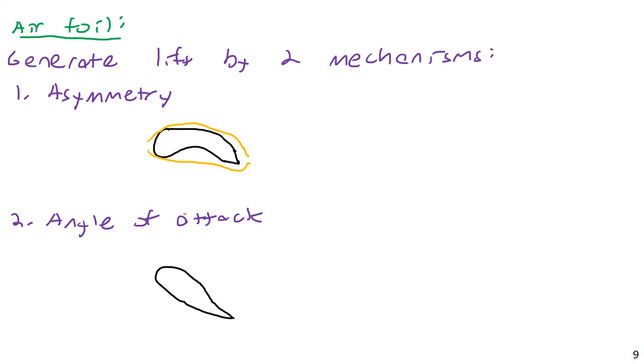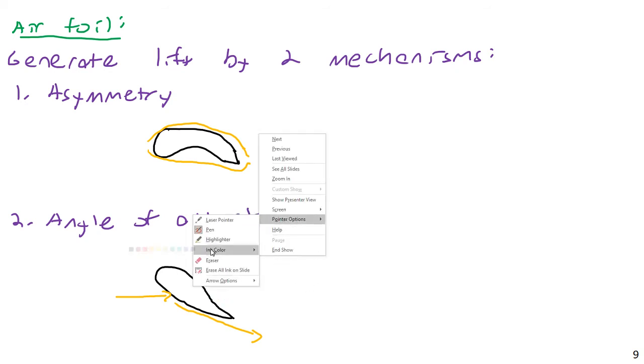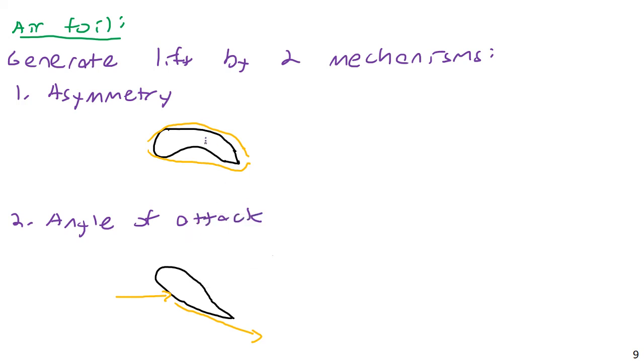It's a resulting force. Another, simpler way to explain this is just a simple deflection. If you have wind coming in here, a lot of it's going to have to be forced downward in order to get around the airfoil. So you're effectively forcing wind downward, and the fact that you're forcing air downward means that you are forced upward.